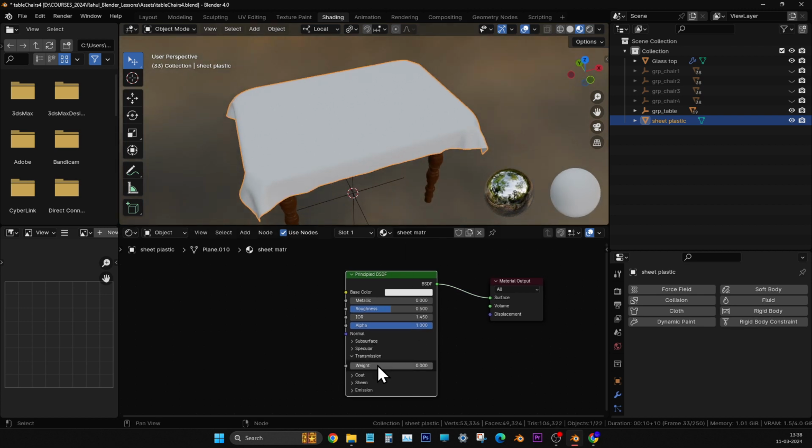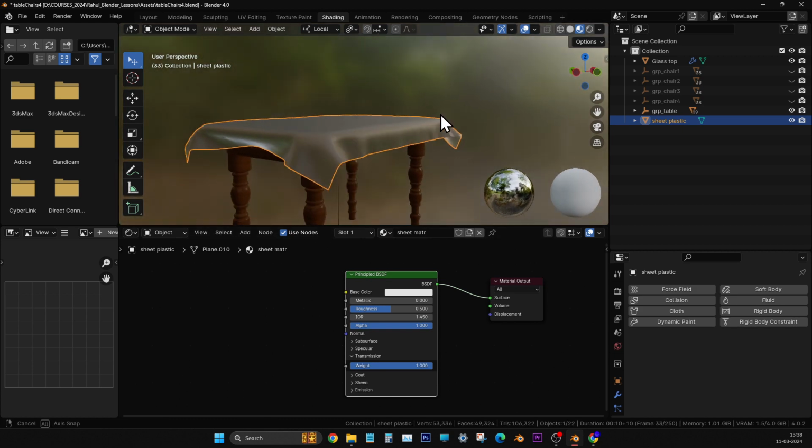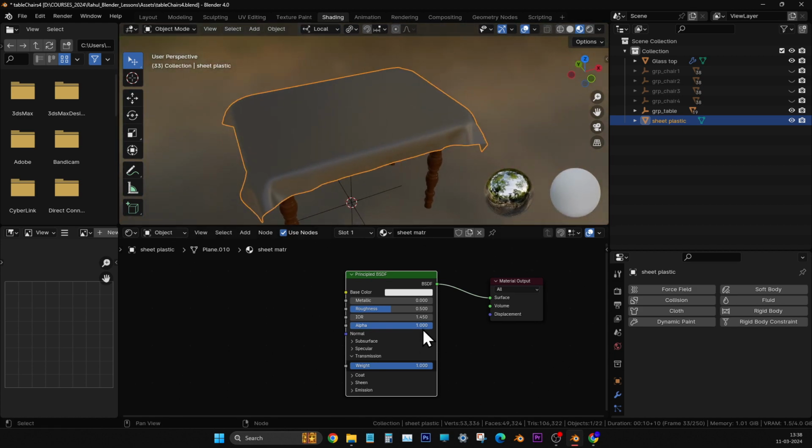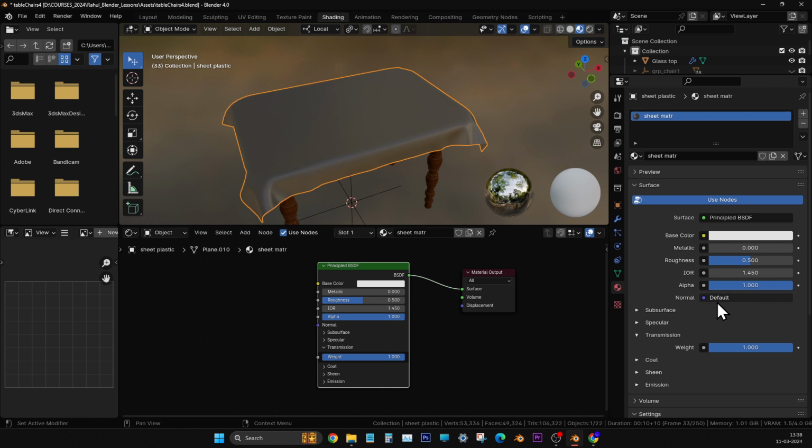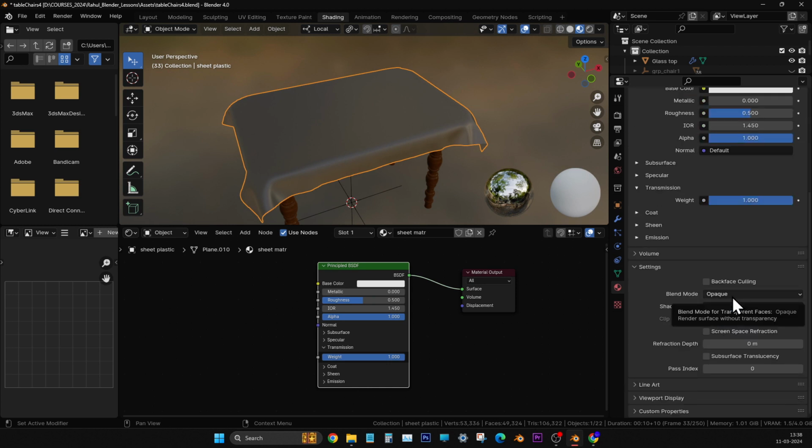Now let me just apply this transparency and see. It'll be like this only, because you know very well, we have to tell Blender that the blending mode should be alpha. Alpha should be on. By default opaque is on. Opaque means non-transparent. So we have to mention every time in Principled BSDF that this particular object should have alpha information, transparency information. Like that, we are changing it from opaque to alpha hashed. Alpha means transparency. Right.